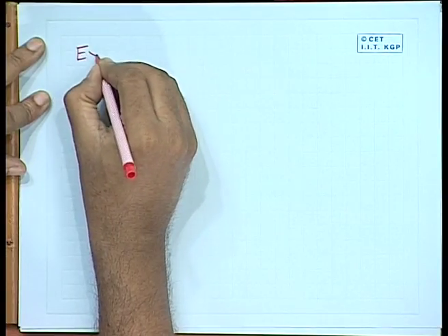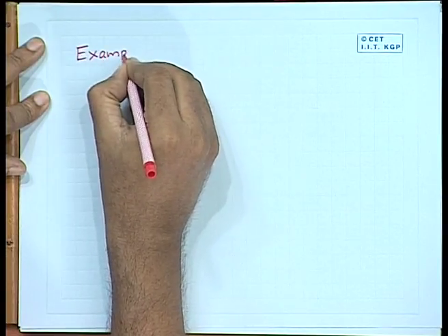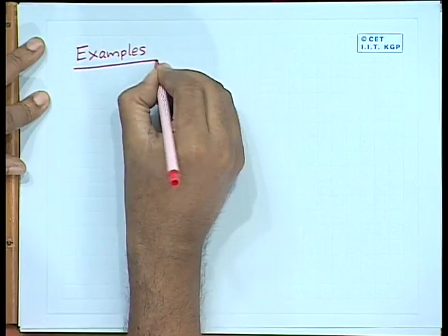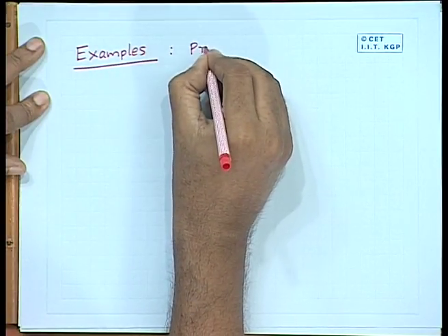There are methods to find out whether a polynomial is primitive or not, and through exhaustive simulation and experimental studies, people have found a list of all primitive polynomials up to very large values of n also. So, I am giving you a few examples of primitive polynomials.